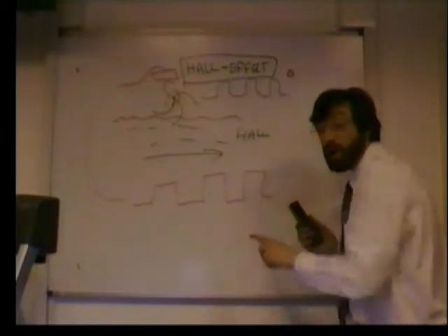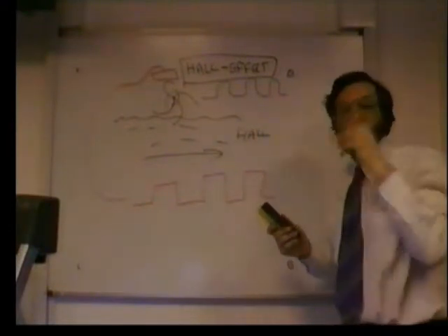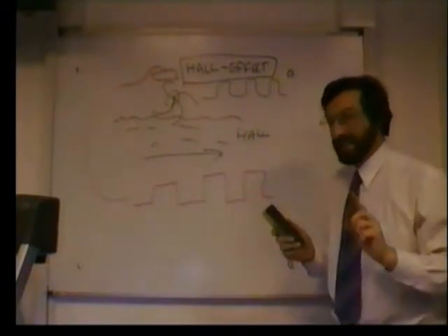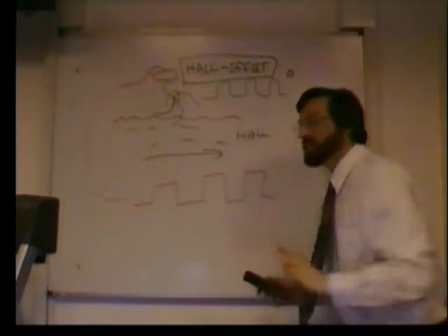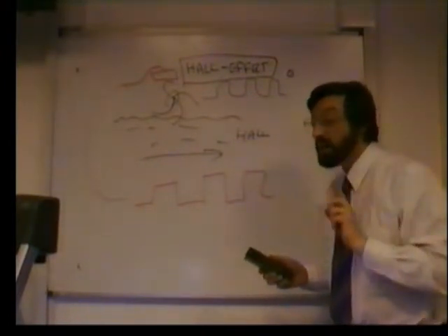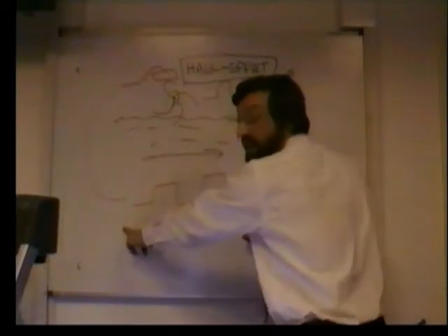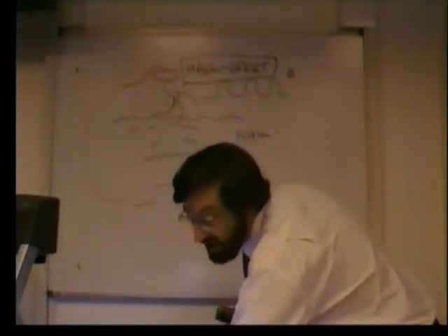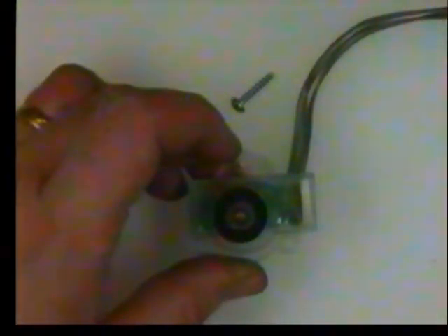Which we can get into a computer. Why is that good for us? Well, computers are fundamentally stupid, but they are capable of counting. And if they can count pulses, so we can measure flow. Even better if they can time them. So we say how many pulses in 100 milliseconds, we can measure the flow rate. So there is another sensor unit. This has come straight out of our shower. Our little turbine meter with a Hall effect sensor will give us a pulse train that can go into our computer.